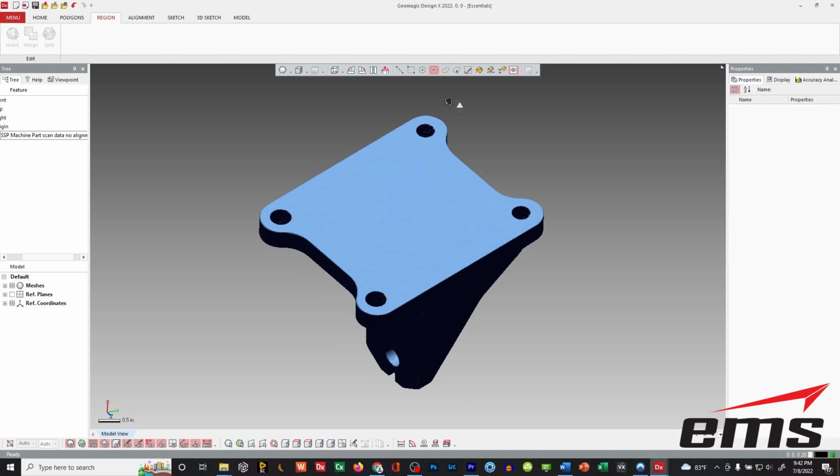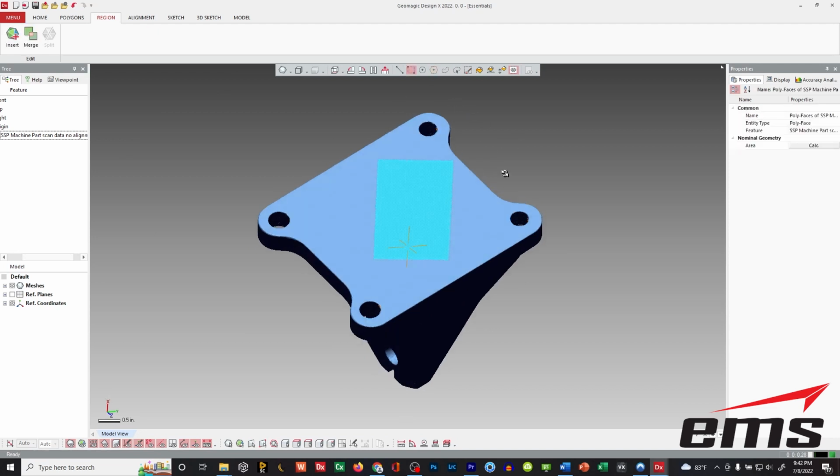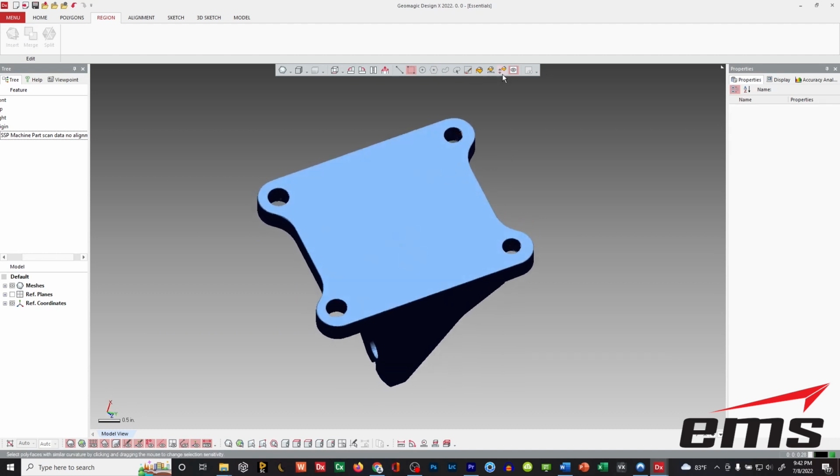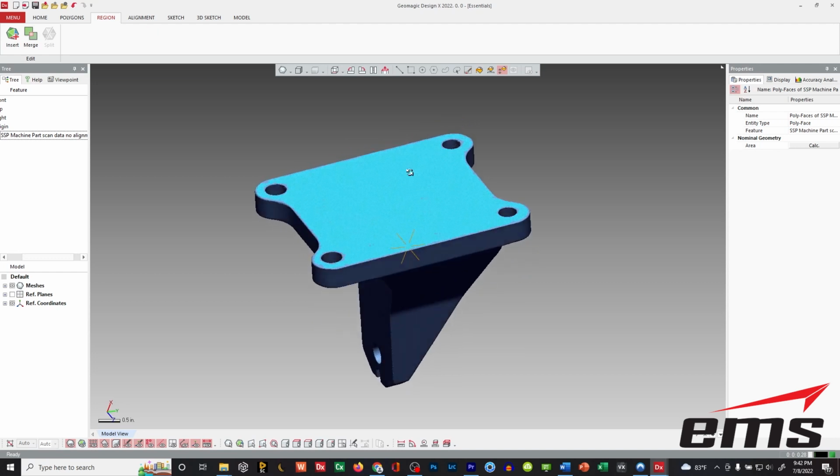There's a square box tool that selects anything that crosses the box. The tool I like to use here is called Smart Selection. You click and hold your left button, and as you move up and down, it looks for similar shaped geometry, and the more I move up or down, the more it expands or contracts.